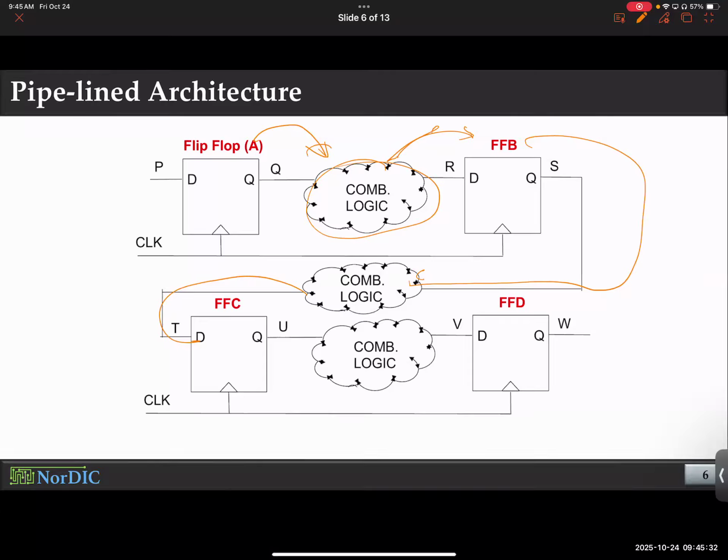So for example, if you take some algorithm courses or maybe computer architecture, when you process different instructions, you have to keep track of how many bits you're dealing with. So imagine you have 16 bits, the first 4 bits represent XYZ. The next 4 bits represent something. The next 4 bits represent something else. So you have to keep track of how many bits you are dealing with at a time. Making sense? So you can use these flip-flops to synchronize that. 1, 2, 3, 4 clock edges. So I send the first 4 bits. This is your address.